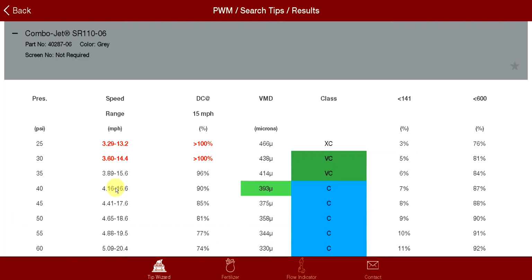So when that turn comp factor is built in, as soon as you start deviating from straight, let's say you're swaying around a slough or something like that, the actual speed on the outside wings of your sprayer is going to change. So that extra room on the duty cycle side of things, up to that 100%, is what you'd get as far as that flexibility into that turn.